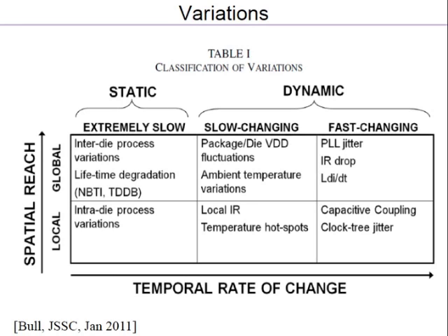Similarly, the channel length. The channel length when the transistor is manufactured is basically defined by etching the gate. You deposit a gate material and then you etch the gate material. The etching is a chemical process. So when the geometries are defined, you will not get a perfect straight line with a ruler. If you really zoom in, you will find a lot of jagged edges. It's a chemical process, it's biting and it's taking out. So you will have jagged edges. So again you see that the notion of a gate length itself becomes a random variable. It has a certain variation. So all this causes variations in the transistors, even though they are supposedly identical transistors.